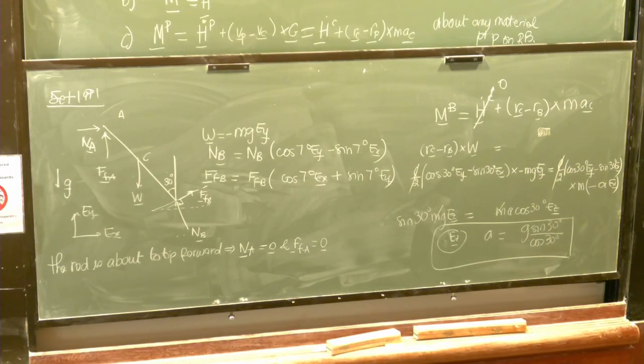How many forces are acting on the rigid body? It's just like the 3, right? Yeah. Okay, so the weight is at the center of mass. So what is the moment of the weight about the center of mass? 0. 0, perfect. One is gone. The other two are applied at point B. What are their moments about the center of mass? The forces times the distance between. You have to use the cross product definition for the moment, okay? So RB minus RC cross the sum of the two forces.